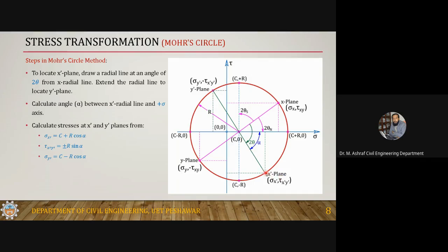Now to get the coordinates of this, one thing you can do is do it fully graphically. You draw a circle to scale and do everything graphically. Just count the squares. You say one small square is equal to this, or 1 centimeter is equal to this, and then do the conversion. To get a particular angle, there is no need to use sine theta. Just use a protractor or a D and measure this angle.